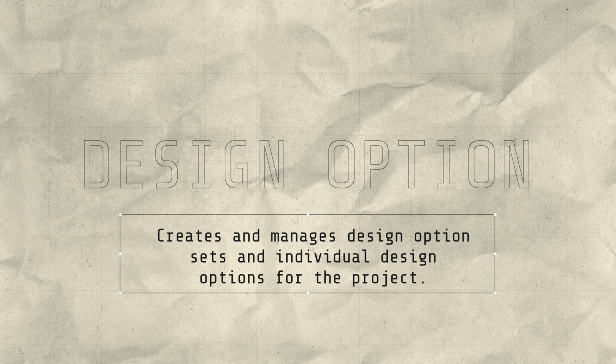One of the best ways that I have come across to design a good electrical room is to sometimes offer multiple options and think of the pros and cons of each one. Revit has this tool called Design Option. A Design Option tool essentially takes the same elements and you can stretch it to different dimensions, you can put them in different locations, you can give it different properties, but it lives within that option.